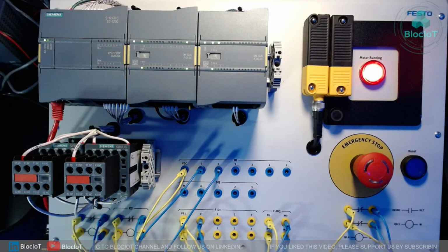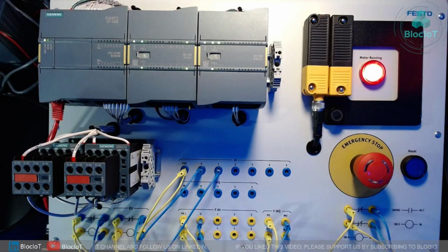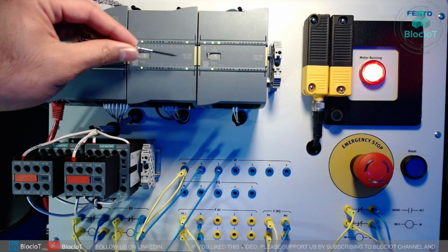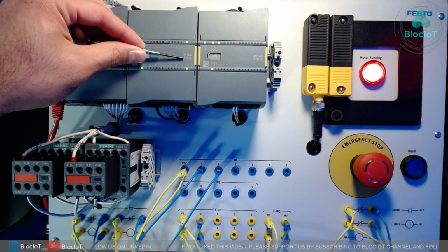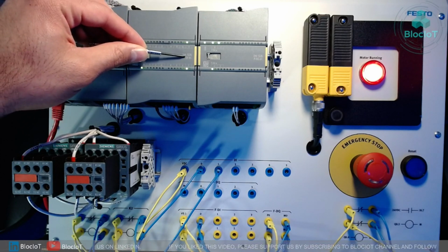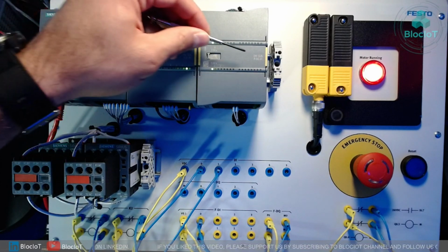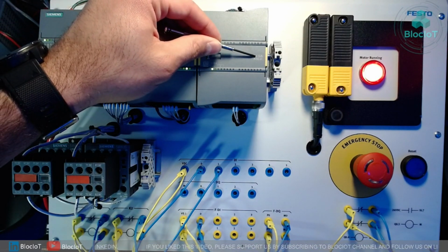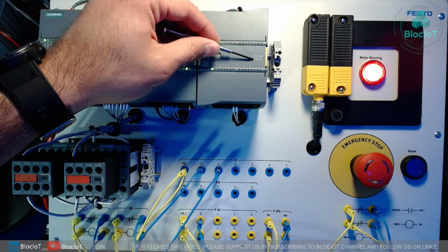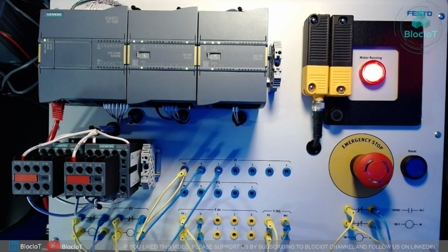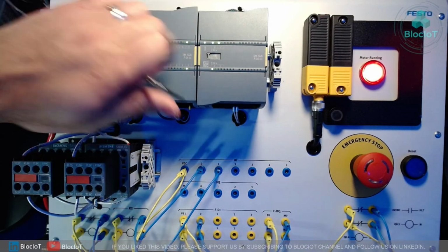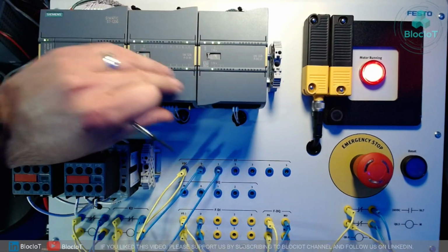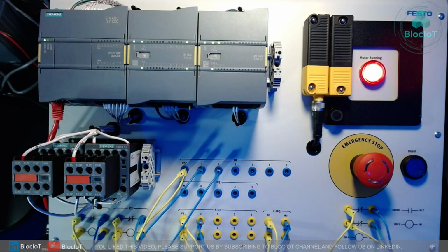So you can just use the CPU for processing a failsafe program, but you cannot use its inputs as failsafe. That's why on the right side, we put a signal module SM1226, which is a failsafe digital input, or FDI, and we also use an SM1226 which is an FDQ, or failsafe digital output. If I'm not mistaken, this is a 4 digital output card, and this one is a 16 digital input card.